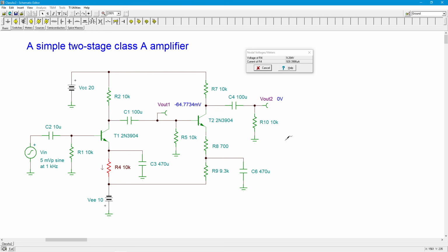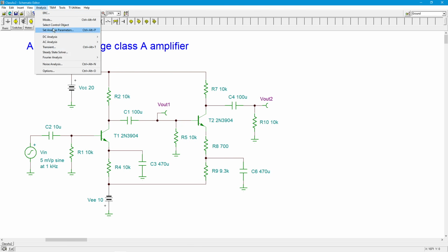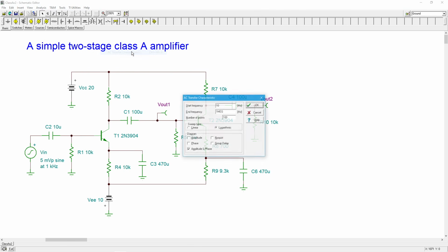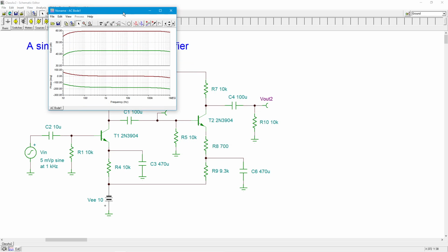So basically, the DC looks fine, right? Do remember this negative 65 millivolts sitting on the base. We're going to use that down the road. It's small. Just remember that it's about 1/10 of what we'd expect the base emitter potential to be. All right. Now let's go and do a real quick Bode plot on this thing. We'll see what we can get as far as a nice gain plot.